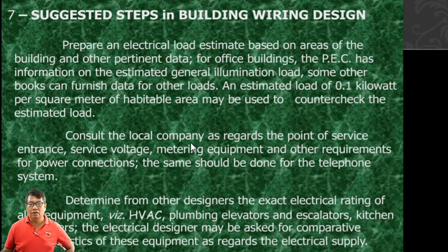Okay, so suggested steps in building wiring design: prepare an electrical load estimate. So gawa muna tayo ng design, saka yung estimate, yung design natin, gawa natin in areas of the building and other pertinent data for office buildings. Philippine Electrical Code has information on the estimated general illumination for lighting. Some other books can furnish the data for other loads. So yun po yung una.